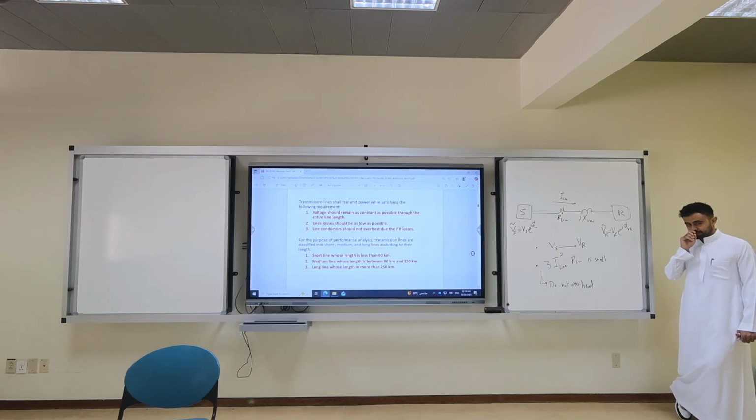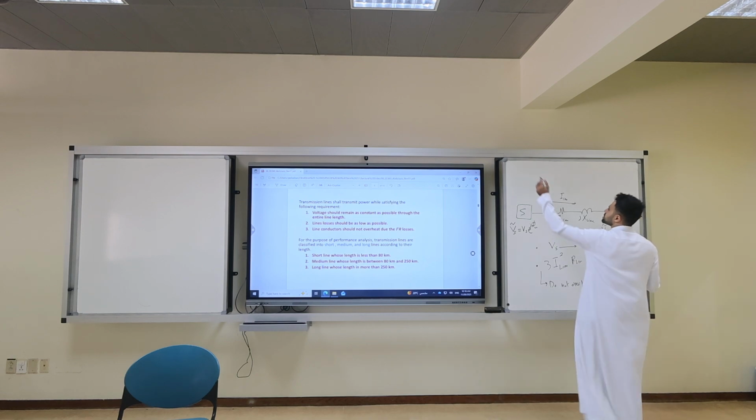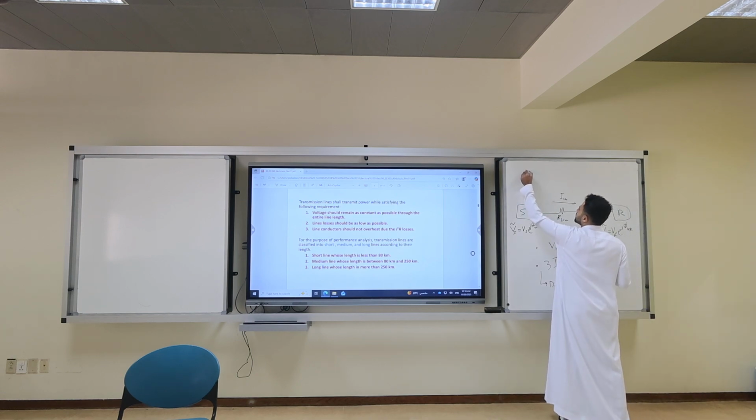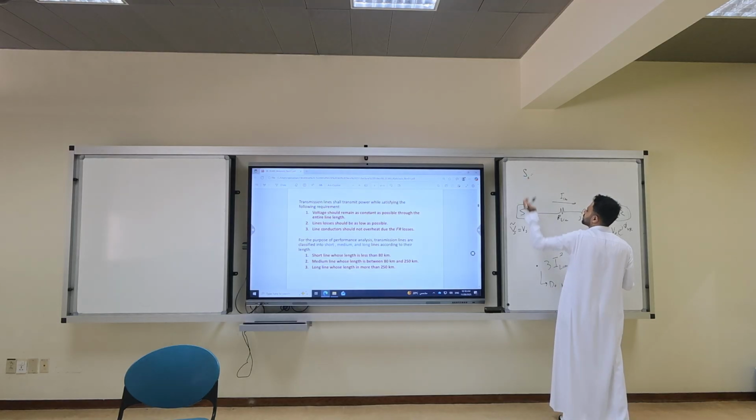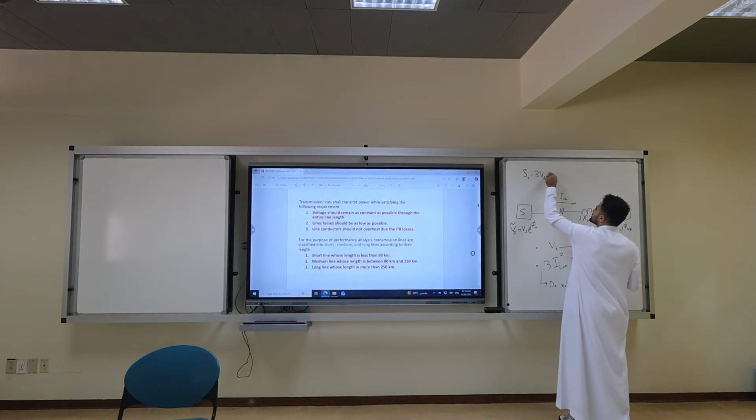Okay? There are equations that I want you to memorize, not memorize. S for the sending end, the complex power that we send, is 3 Vs I line conjugate, or you can call it 3 Vs I send.